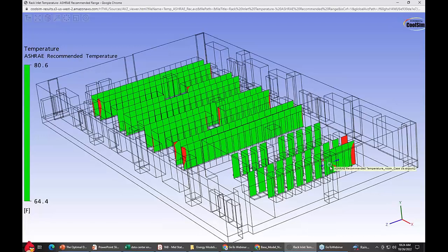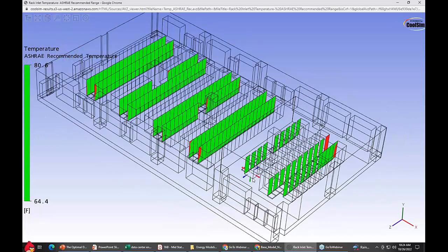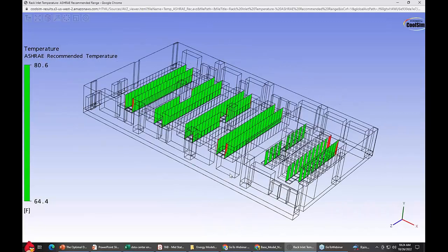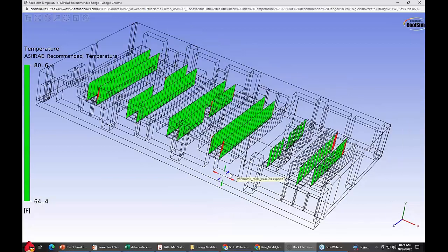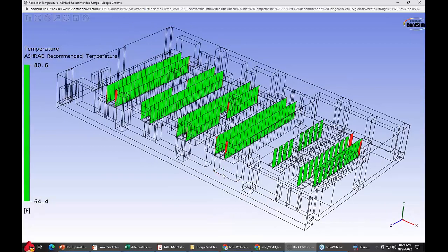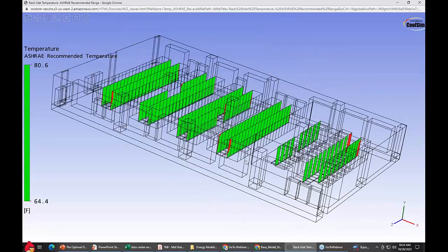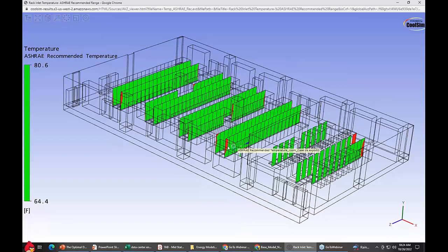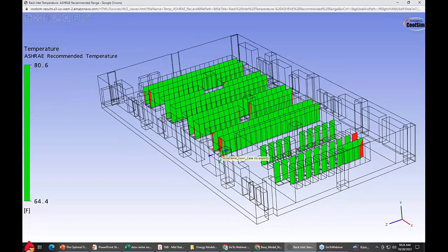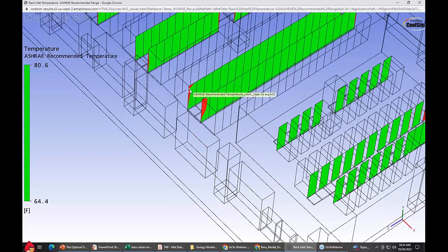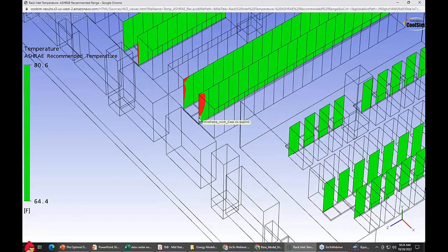For those of you who grew up in the United States, you would know what that is, because Visine used to sell advertising for getting the red out of your eyes. For bloodshot eyes, you use Visine, and we used to call these Visine charts because we were trying to get the red out. So that's the joke you probably won't get unless you grew up in America. But yeah, this one's okay. Read along these sections, this isn't unusual because that's right on the edge. The chances are that's probably okay because you're not going to put servers in that section anyway. Most people who are doing data centers understand that that last tile is problematic.